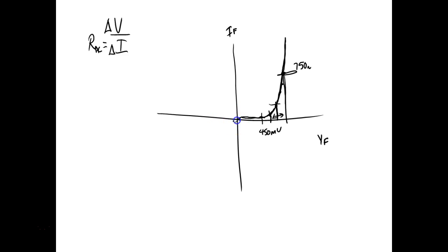Then we're going to do this as a class. We're going to come over here and do this, and we're going to break the thing over. Now, how are we going to get by with that? Well, what we're going to do is come up here and use like a 10 mega ohm resistor. So when it does break over, there's not going to be enough current flow through it to do what? Burn it up, right? Understand that?